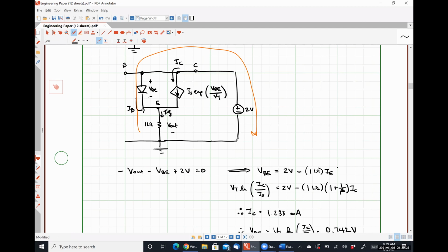Yeah, they're the same thing, right? So this circuit is built to operate right on the edge between saturation and the forward active region. So our model is still okay, but it's right on the cusp of being unusable. And that's the way this guy's designed.